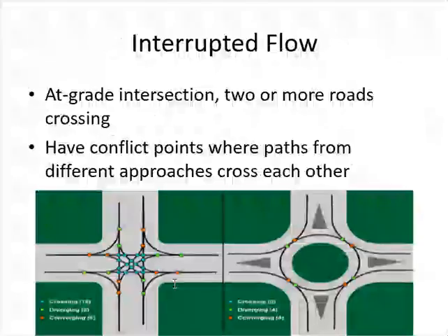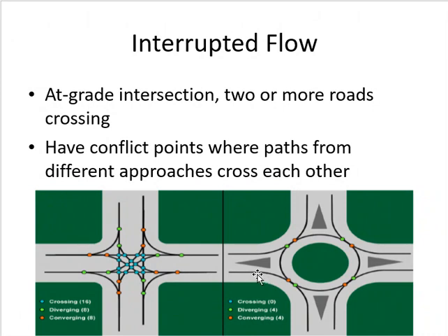If you look here, see, the angle is reduced. So this guy cannot go this way, and nobody can come from this way and hit him. So even if somebody makes a mistake on the roundabout, the angle of collision is less. So there's a higher potential of ensuring safety.